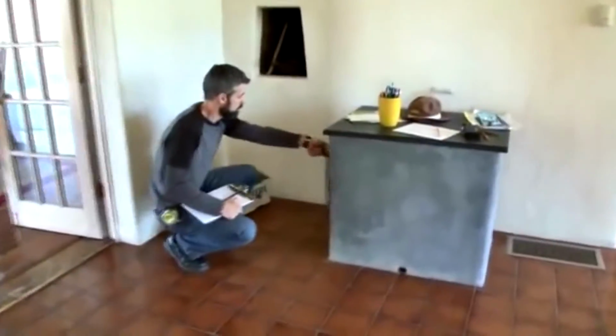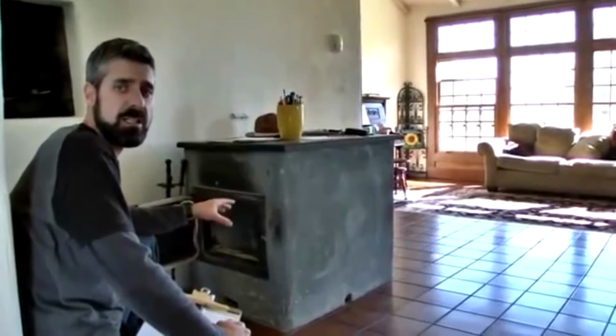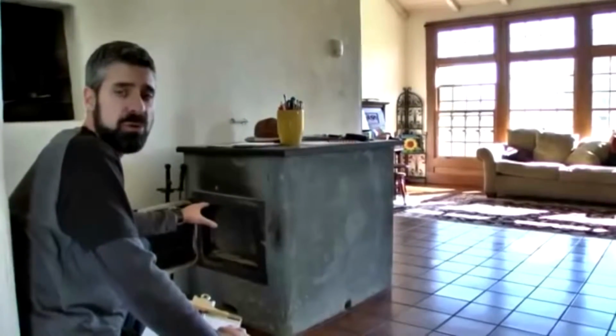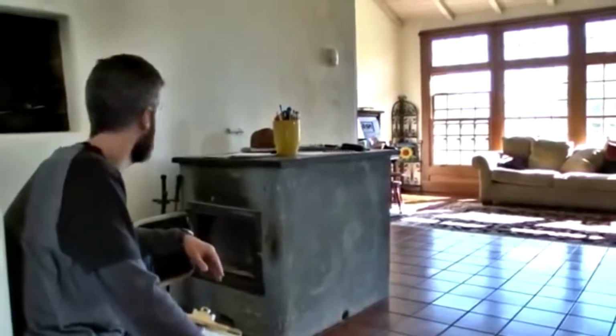Pretty cool wood-burning stove, it looks like. Now this brings up another interesting point. For anything that's wood or coal burning, you want to make sure you talk to the client ahead of time to ensure that they haven't been using this for a period of time before the blower door, so that this unit can cool down and you're not potentially sucking hot coals out of it into the living space when you're doing the test.